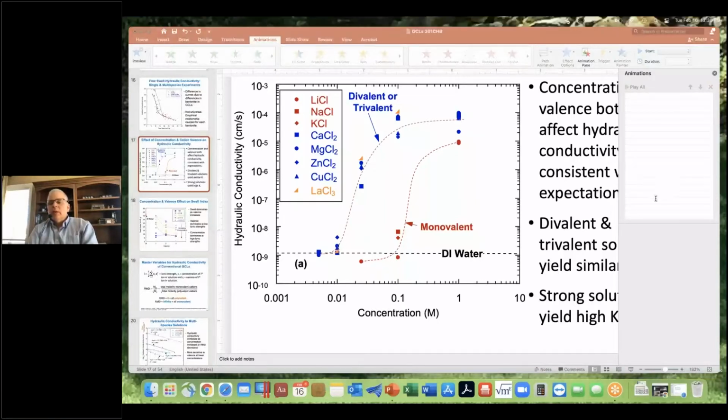Question from Calvert Barclay. What do you think about considering degree of saturation as opposed to equilibrium water content? Yeah, good question. I didn't really talk about this, but usually we run these tests so long to get hydraulic and chemical equilibrium that they are completely saturated. One of the things I do check when I complete my tests is, and I don't very commonly run a B check, but I will calculate the degree of saturation based on weight-volume calculations at the end of the experiment. They are inevitably within 90 to 110%. There's a little bit of error in that calculation. So I use that to check whether it's saturated.